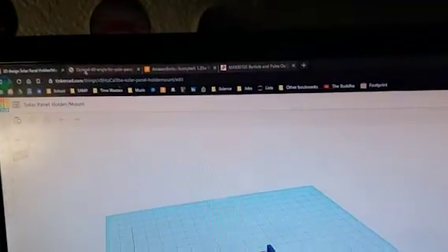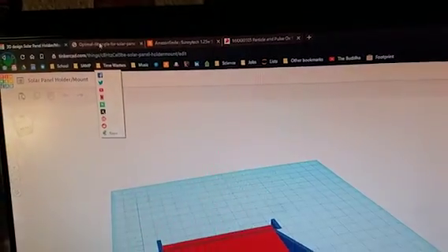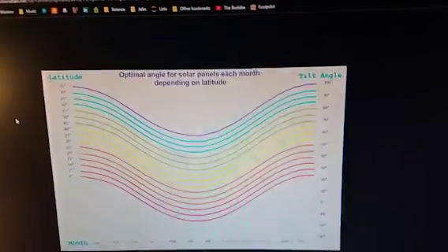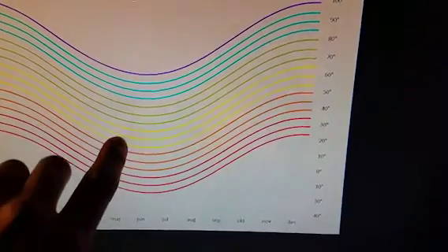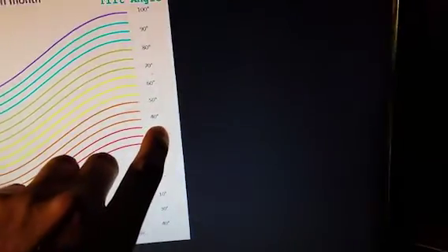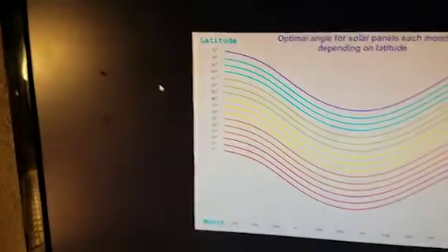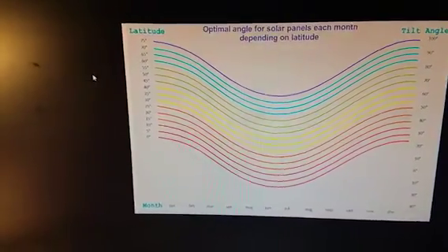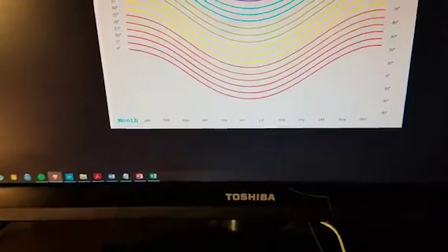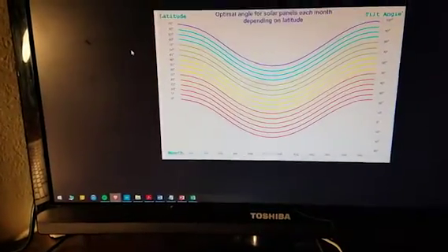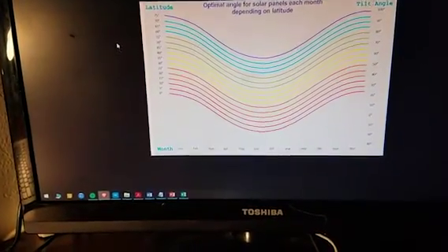The reason I chose 35 degrees is because at our latitude, the best tilt at our time of year is a 35-degree tilt angle. So this is kind of like a solar panel latitude to tilt angle conversion. But overall, I took a solar panel class last year. 35 degrees is recommended for us, like a static, locked-in, fixed tilt system.